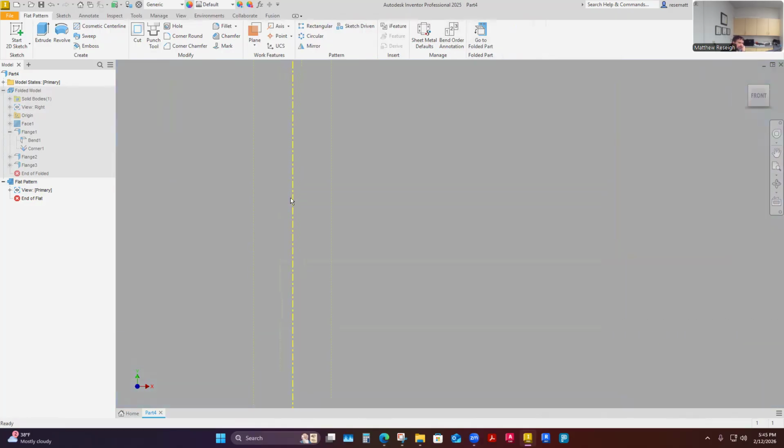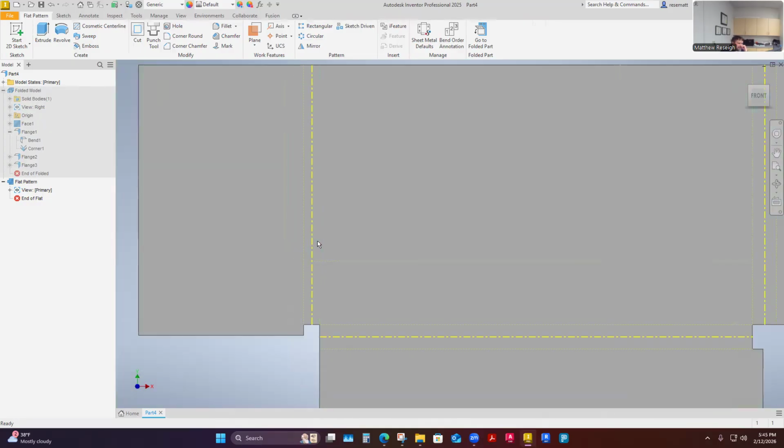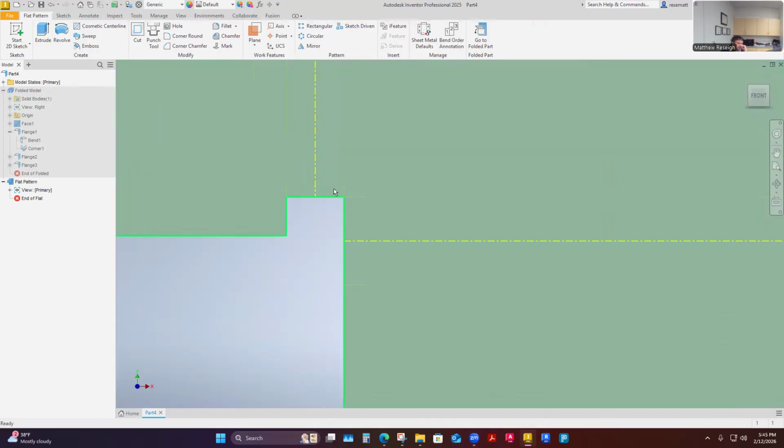And so what I'm looking at here that are automatically applied is this is kind of the center of bend, kind of where my machine's going to come down and hit that center mark and bend it. These dotted lines are the bend extents. So that's kind of the parts that are going to be compressed and stretched in that bending when that happens. So it's kind of bend extents and center of bend. Just automatically applies those.